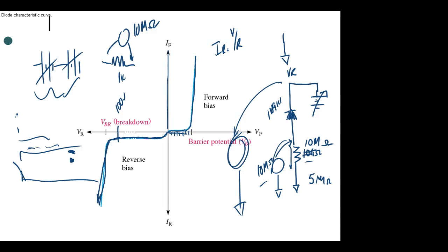And then we're going to get a can of freeze spray. We're going to spray it on there, and we should see it go to almost zero, because freeze spray is cold, right? Freeze spray is a troubleshooting tool that we use. We spray it, and it's really, really cold. A lot of things operate when they're cool and stop when they get hot. So that's the way we figure out which one of them is doing it, because it's an intermittent problem.